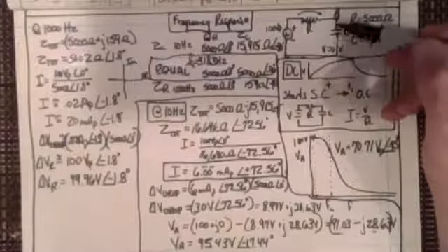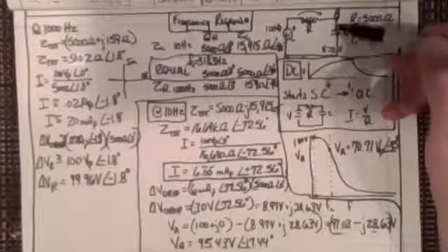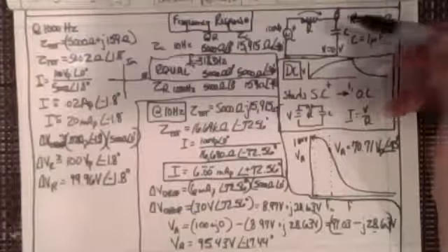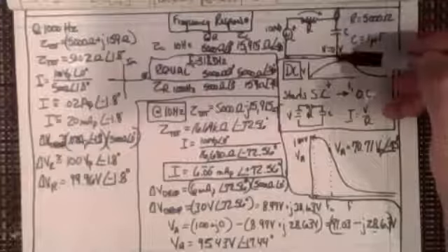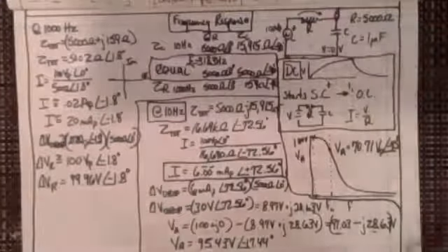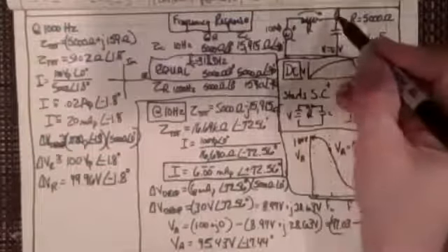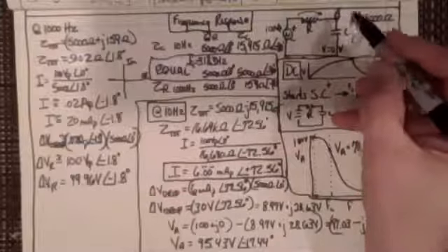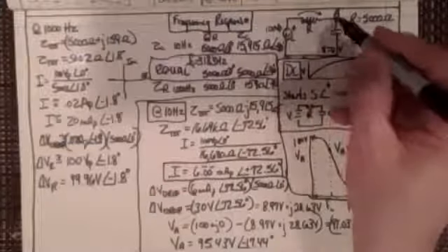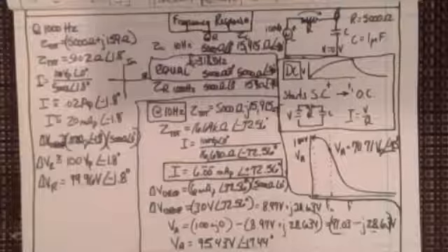This is holding off more voltage all the time, low frequency. At high frequencies, the voltage is just flowing right through the capacitor, and this is going to 0, and that's why you get the 100 volts across it. All right. Okay.